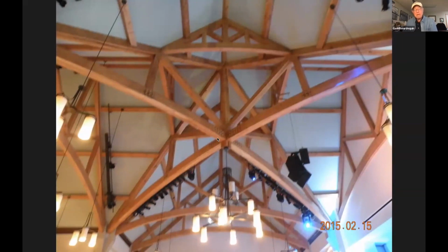The most I've ever done is 3, but in order to do that, the distance between each row has to be 5 inches. And then you have to have 2.5 inches of edge distance out to the side of the timber. So if you were putting 3 rows of bolts in this glulam, it would be 15 inches deep.